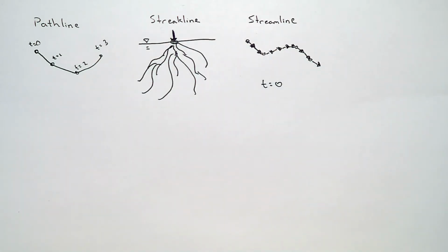So how do streamlines and path lines differ? Path lines require a finite set of time. You need a range of time. However, streamlines can be taken in specific time snapshots. Path lines are lines for one individual particle moving. Streamlines are lines for multiple particles at one individual time step. Okay? So streamlines and path lines.